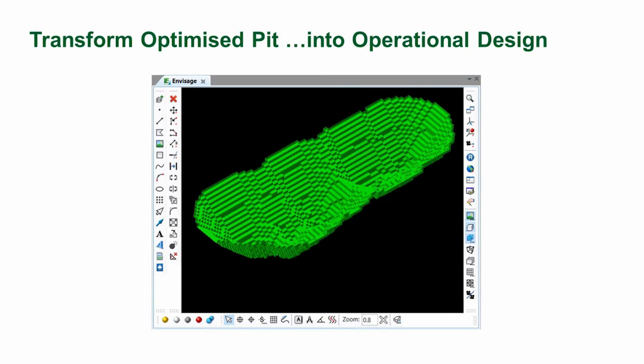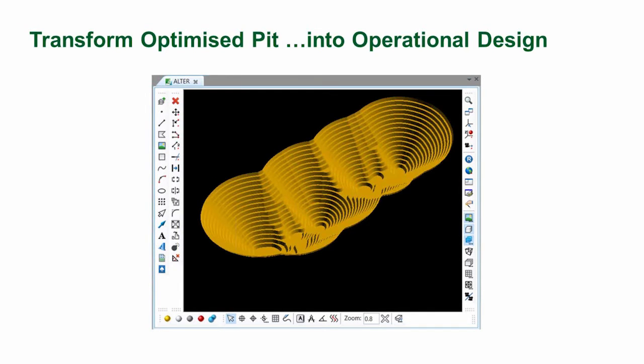Well, you are absolutely right. You take the result from an optimization, essentially a pit shell, and use the result to create some preliminary pit design, essentially toe and crest, but in an automatic way. So this preliminary design should consider at least obeying batter and berm configuration, incorporating the majority of high grade presented in the optimization, obeying minimum mining width constraints, and so on.